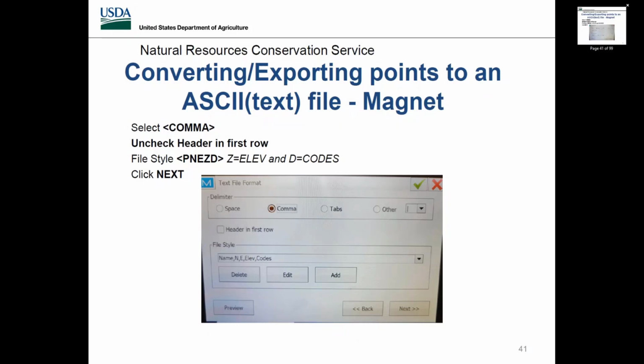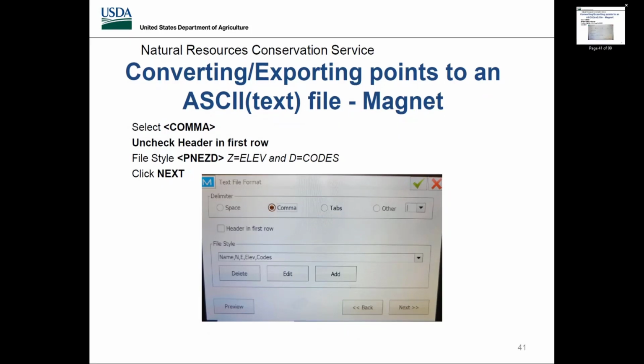I've just always used, at least on this one, the name, and maybe that's why I never ran into that problem. I haven't seen it come up. But that's a good catch. I've had a couple times where some of my points just kind of disappeared because I accidentally put some letters in there, and if you just do the PNEZD, it'll never show up. Right, I gotcha. That's good to know. Thank you for that. Be more careful.